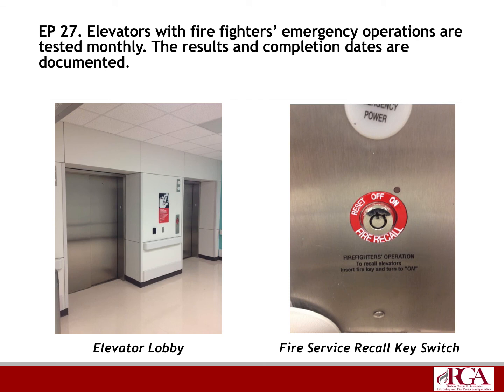EP27. Elevators with firefighters' emergency operations are tested monthly. The results and completion dates are documented. So this is your fire service testing. It's performed monthly. This has always been into play. It was added into the 2018 EP standards, but it's always been a requirement.